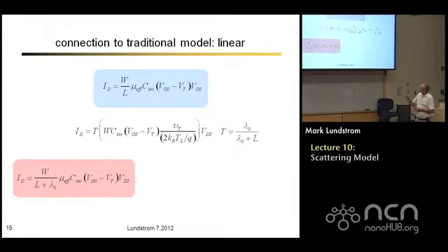So that looks like the traditional expression, except that I replace the channel length by the channel length plus mean free path. Just algebra, right? That's all it is. Now that's kind of nice, because now as scaling takes the channel length to 0, you don't have to worry about things going to infinity. They'll go to some finite answer. And you ask, well, why in the ballistic limit, when the channel length goes to 0, is there a mean free path downstairs? But remember, there's a mean free path in the mobility. The two just cancel out, and there is no mean free path in the ballistic limit.